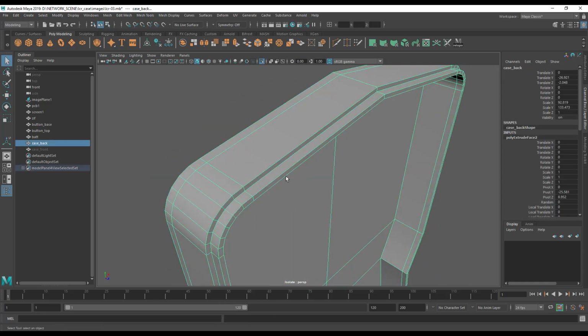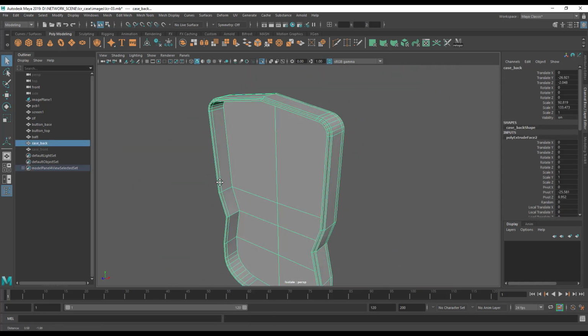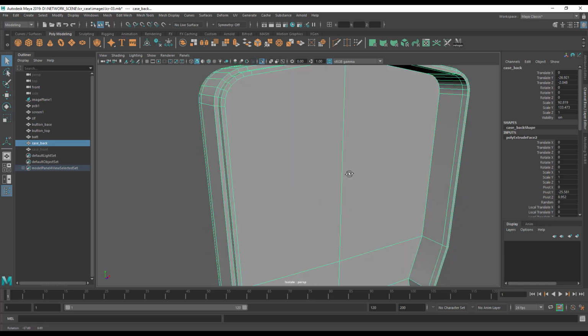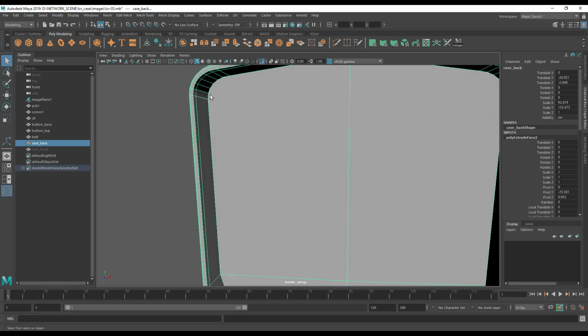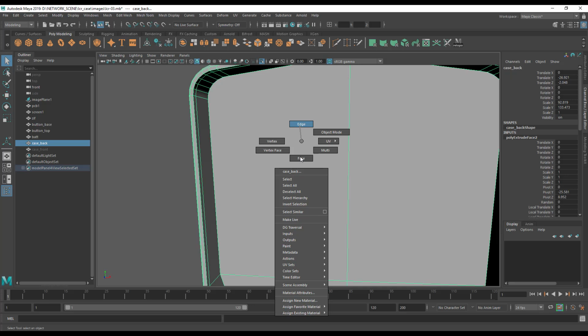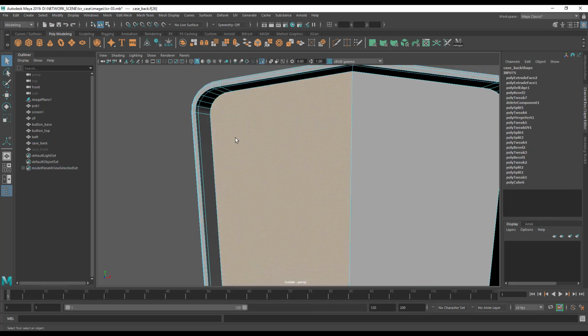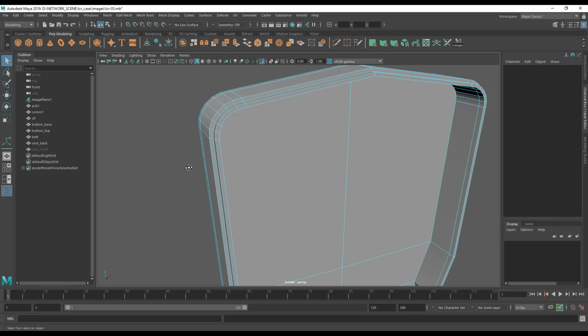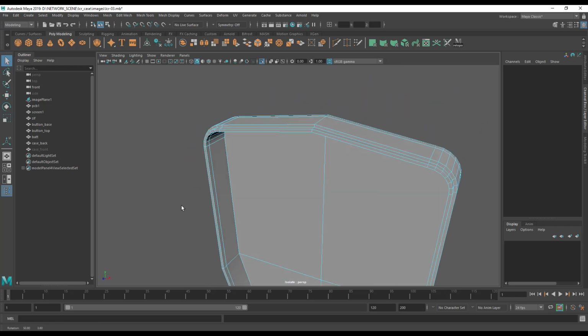And there we go. Now, one thing we can do to make sure we've got no non-manifold geometry, because the geometry on this from a Maya point of view, what I've got here is an n-gon. As I explained before, this polygon, this one here, now has more than 4 sides. This is generally frowned upon with Maya, because if I wanted to bend or flex or run a simulation across this thing, it could cause potential problems. In the realm of 3D printing, it's no problem at all.